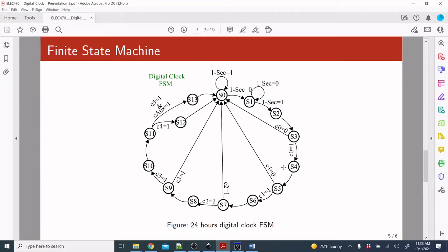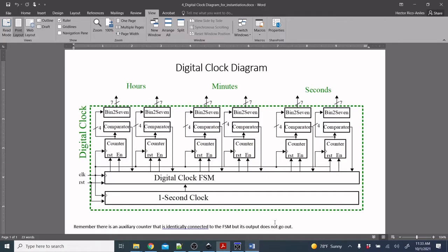That's when your counter will reach the count and is going to be reset. But there's a problem here, because to get to state 4 from state 3, we need the output of the comparator 0 to be 1. So we need a 1 here to generate this reset to make this 0.